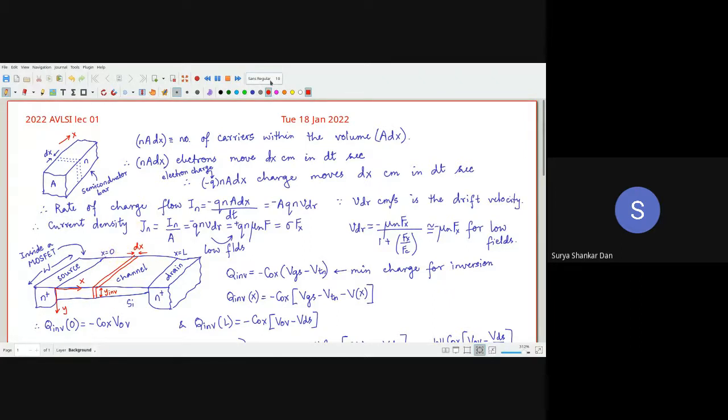So the gate will be something like this above. Okay, so if the channel length is L, as you can see from the distance between the source and the drain, is capital L, then for the micron technology, large devices, this capital L will be in the order of close to 500 nanometers or so or higher. In those kinds of devices, obviously the distance between the drain and the source is so large that, as a consequence, the field will always be low.